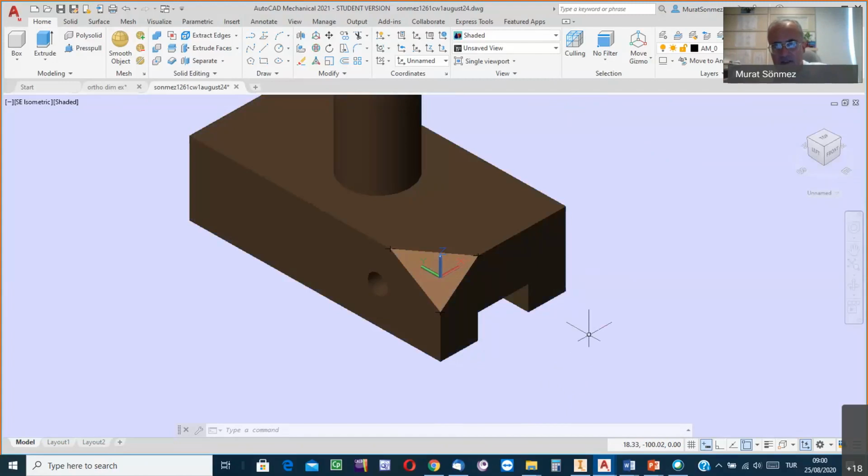But I said, instead of inputting width and height values, if you're going to input the coordinates of the corner points, then it is important: if the corner point to mark, relative to the first point, is in the negative direction of the coordinate axis, write the coordinate value as negative.